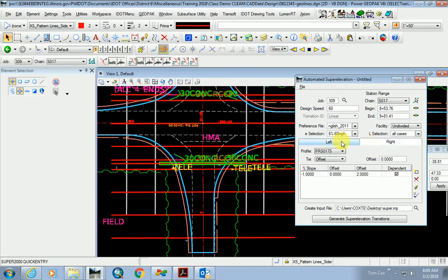And then we have dependent shapes and independent shapes. What the dependency is, it's upon the proposed profile. So you're going to see this shape, which looks like a MicroStation shape. It's going to be adjacent to the center line. And that shape is going to get its intelligence of the elevations because it's adjacent to center line and the proposed profile. So that's what dependency is.